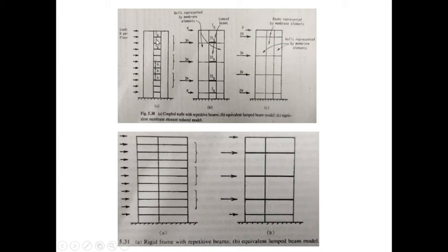So what is done is, these beams which are there will be lumped into one model. At the top and at the bottom you keep it the same, whereas in between we lump it vertically. So 3 beams are clubbed into one, 3 LB. Again 3 beams are lumped into one vertically, and they will be represented here. That is shown here, lumped beams 1 2 3. So these 3 beams together are shown here. Again the next 3 beams are shown here, right?